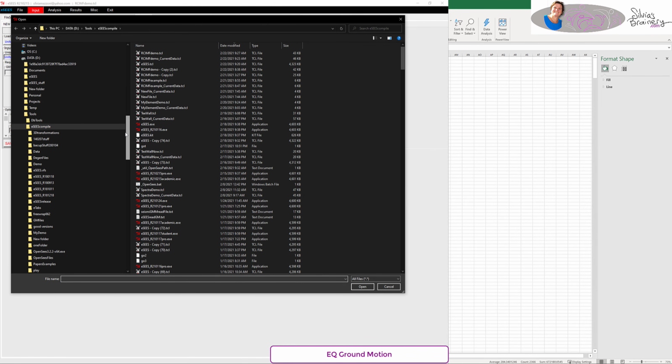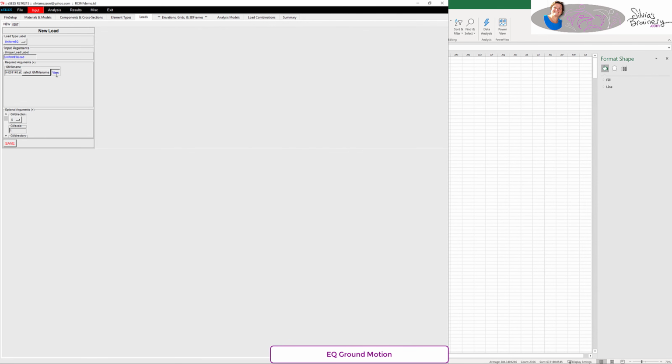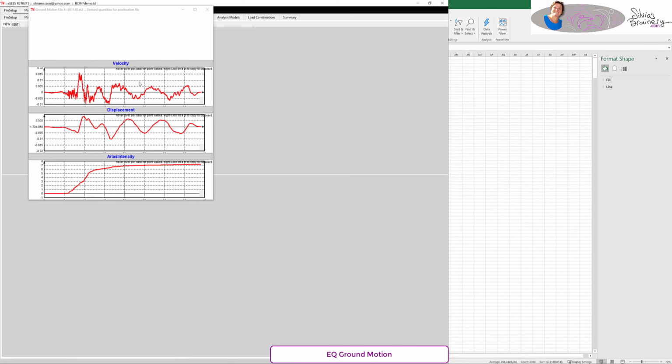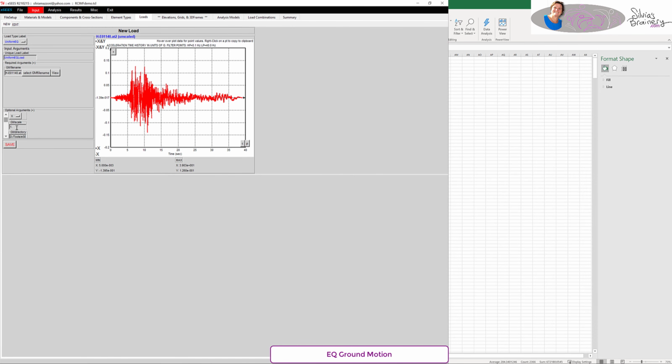Now I'm going to do an earthquake analysis just to show you how easy it is. You go in, you pick a ground motion that you have, you can visualize it even. I integrate the acceleration history. This is just from the PEER Ground Motion database. Interestingly, it's a really old version of the file. I'm going to scale it up by 10 just to make sure.